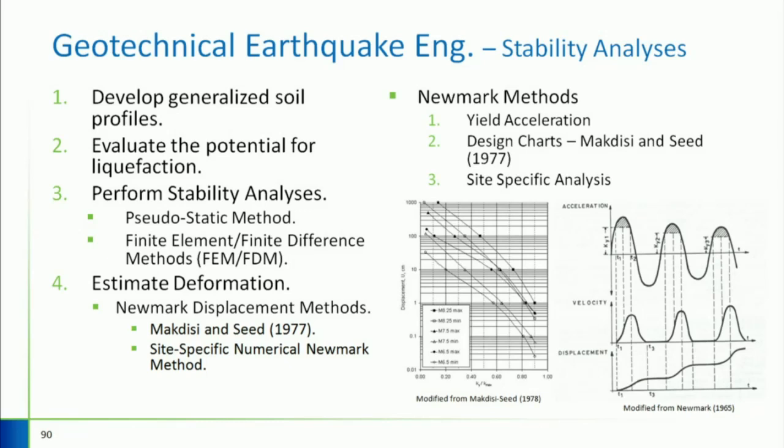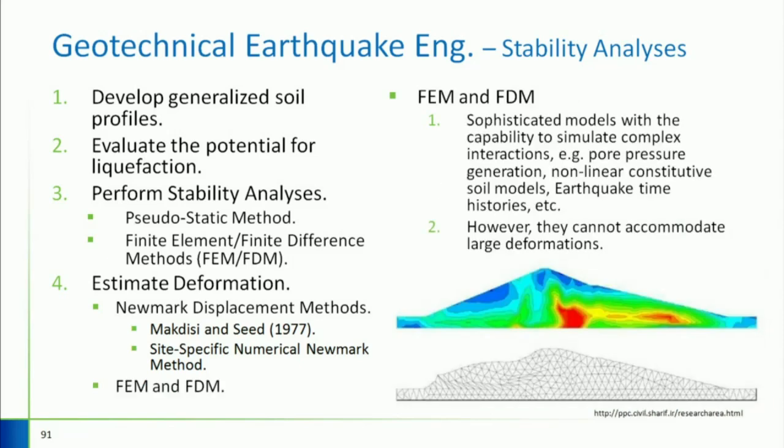And you can actually estimate the amount of this movement by running your time history through a Newmark analysis with a specific yield acceleration that can also change with time if you make it more complicated. And there's also finite element, finite difference.